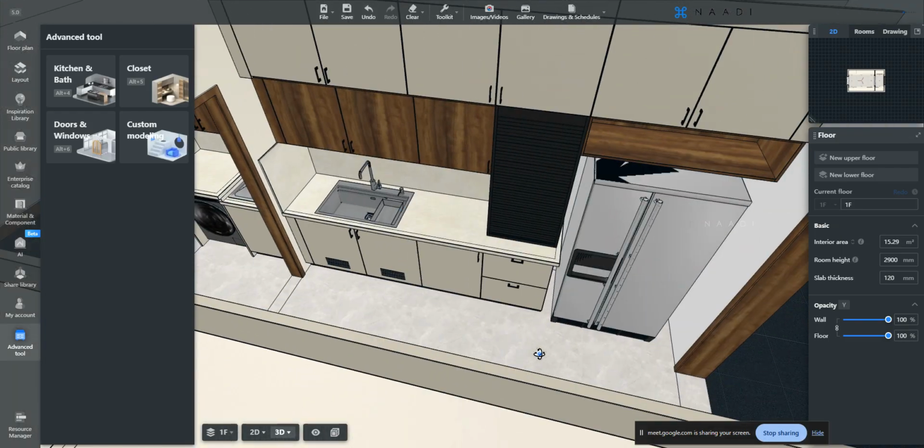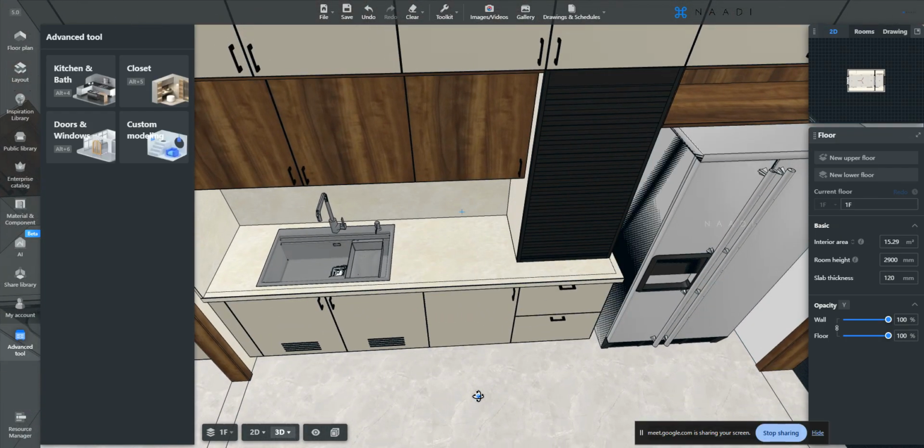See, the thing is, if you follow the modeling workflow which was addressed during your professional course, you won't face any of this issue. The snapping advantages, right? Just do it one by one. Place one cabinet, adjust the width and depth first, and right after that you just have to snap a new cabinet to it. That's it. Only you can adjust the width, the depth and height will be automatically maintained.